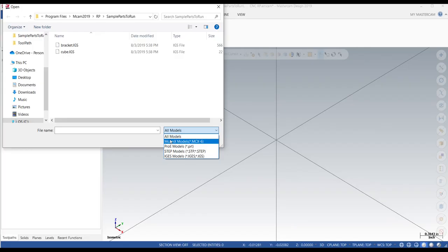More importantly, Mastercam tends to change the unit type when opening an STL file, causing many models to go from inches to millimeters or vice versa. This causes a lot of problems when importing our units into our file and can tend to mess up our tolerances. This can be bypassed within Mastercam by scaling or changing to the correct unit, but you will lose a level of exactness because of this. So I would suggest just using either an IGS or step file.